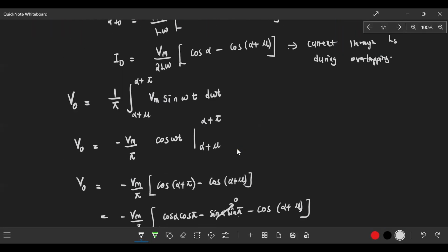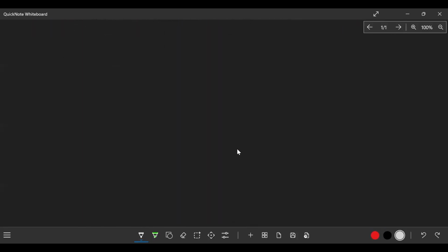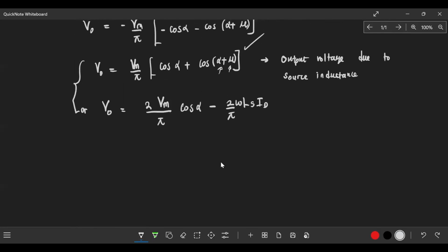So the equivalent DC circuit is this, right? This part here, remember, is DC output voltage. This one will be more like the source, and then the drop is the voltage across the inductor, and then you get the output VO. So these two are in series, as you can see. To get the output, subtract what? The input DC voltage minus the drop.